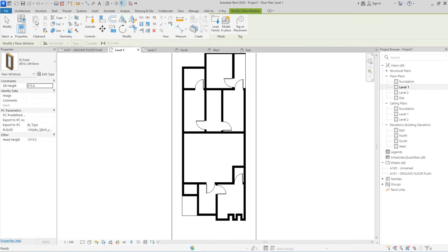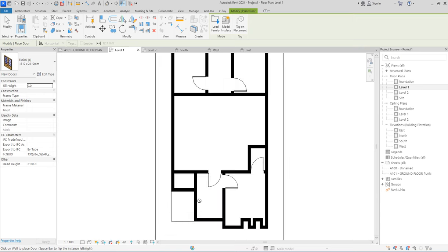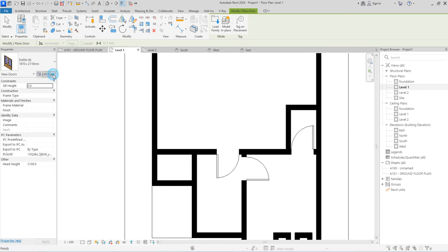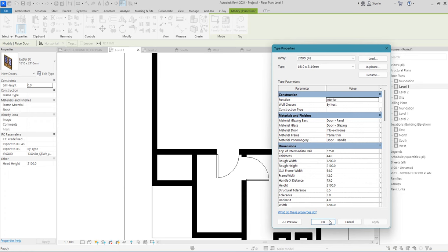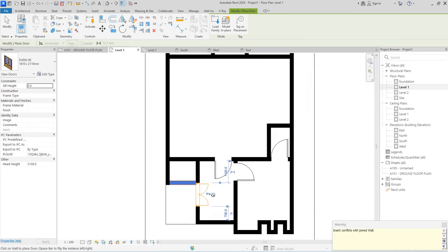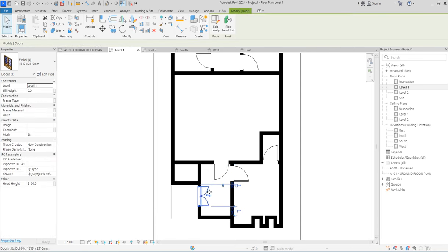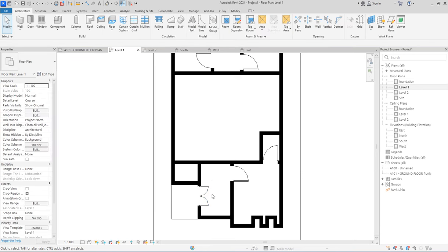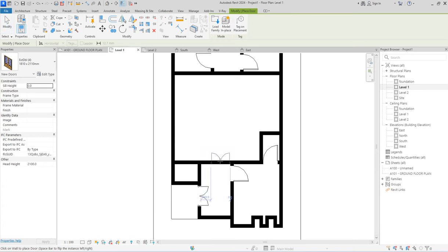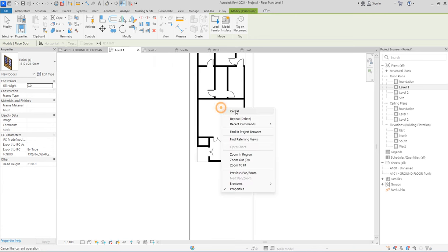So the next thing, we create the door again. Press door, the double door. So you're going to open the double door here. Check the dimension of what you have, 2000 by 12, which is okay. So you put the door here, press escape. Then you remove this one particular one too and put the same thing. It's going to be here as well. Good. So I am done with what I need to do at this junction.